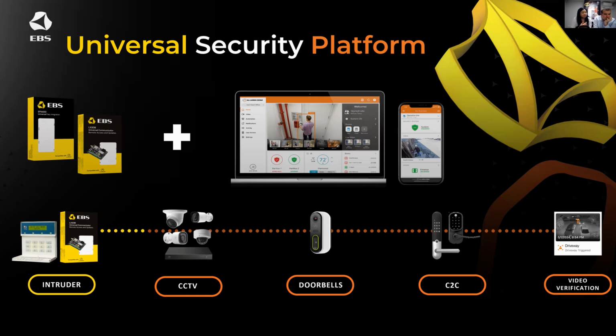We also have other questions that you might want to read. Our Paradox and Adamka can be accommodated by EPX 400. Yes, so the answer is yes. The answer is all control panels with physical input and output, at least one free, not being used for intruder zone. It needs to be a key switch zone, and PGM programmable output. It needs to be free. With that, this is possible.